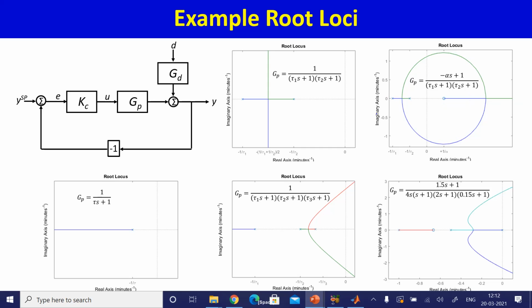Okay, here is another example of a third order system. This is a net third order system. Right? There is another pole that is very far away on this side, but which is not shown, and this example we will be doing subsequently, so you'll see what I'm talking about. But there's a pole here, there's a pole here, there's a 0 here, and then there is a pole far away, not to scale. So you get plus minus 60 degree asymptotes, 180 degree asymptote. So this would be the 180 degree asymptote.